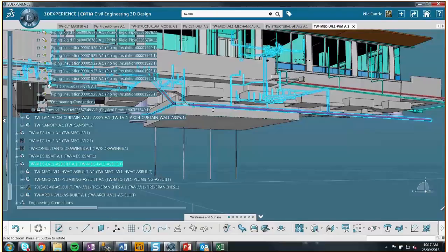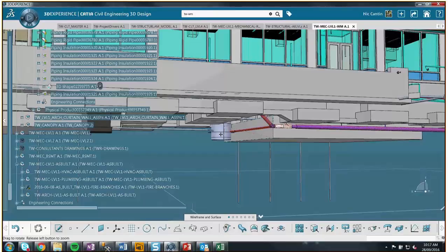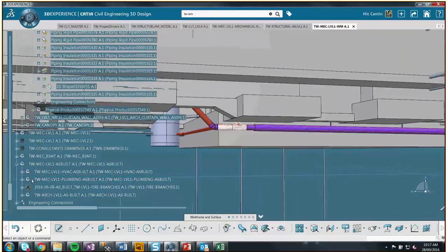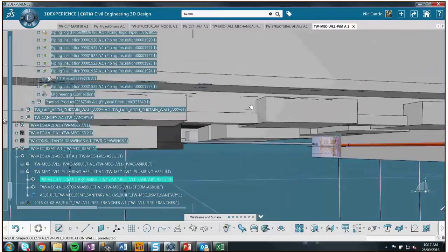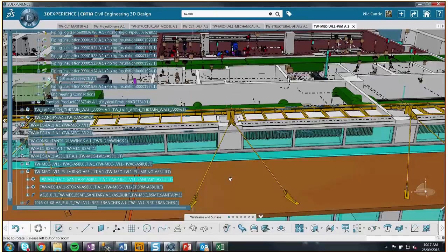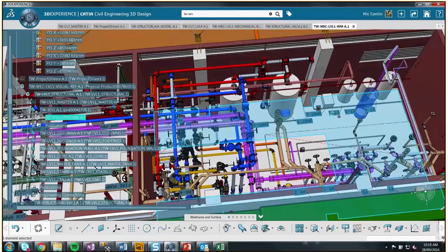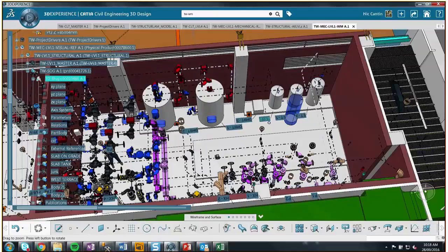Basically, what we needed to know for prefab of the mechanical room was where the final locations ended up being, where the cans actually ended up being in the slab below. If I remember correctly, maybe it's not in this model, we had another surface that represented the as-built before we started. They provided us floor drain locations and penetration locations so that we knew where we could place our equipment without interfering with the floor drains.